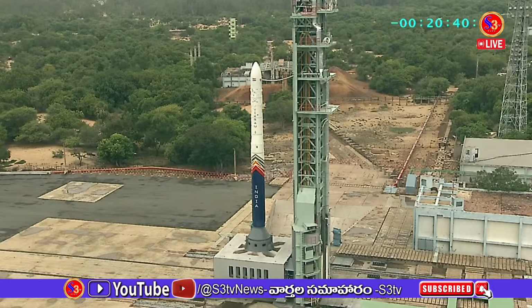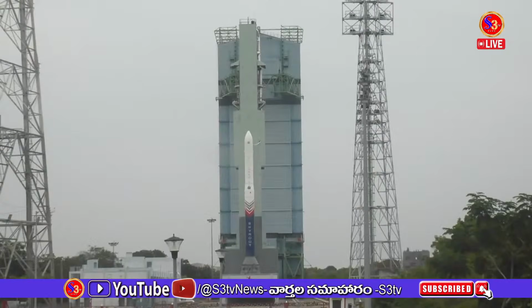That's right, Akhil. And I believe different parts of the vehicle handle different pieces of that. So on the way up, the solid rocket motors steer in pitch and yaw by swiveling their nozzles. Roll, which is the spin around the rocket's own axis, is handled separately by a small dedicated liquid system during the climb. We have a set of 4 thrusters which fire in pairs to control the roll of the vehicle. And once in space, the vehicle does its own pointing with the help of small thrusters, which Suyash will tell us about.